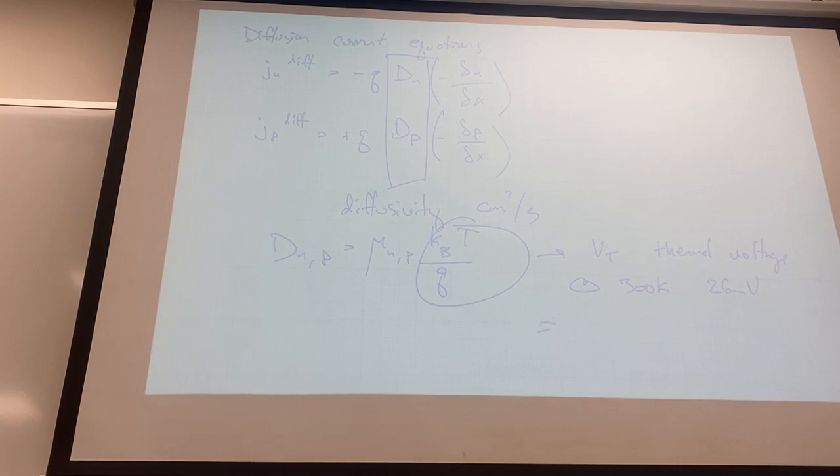This is not V sub little t, the threshold voltage. Get ready to mix these up a lot. The threshold voltage is what we describe in MOSFETs as sort of that magic point at which the transistor can be considered on. It usually takes maybe 200, 300 millivolts, something like that, before there's enough of that conductive bridge between the source and drain to do anything. Until that happens, until you get what we call inversion, until you get enough carriers pulled out of the depths, out of the silicon lattice, nothing happens. So below the threshold voltage, the transistor isn't doing anything. And once you get past this sort of magic number, it suddenly pops into a different region of operation.